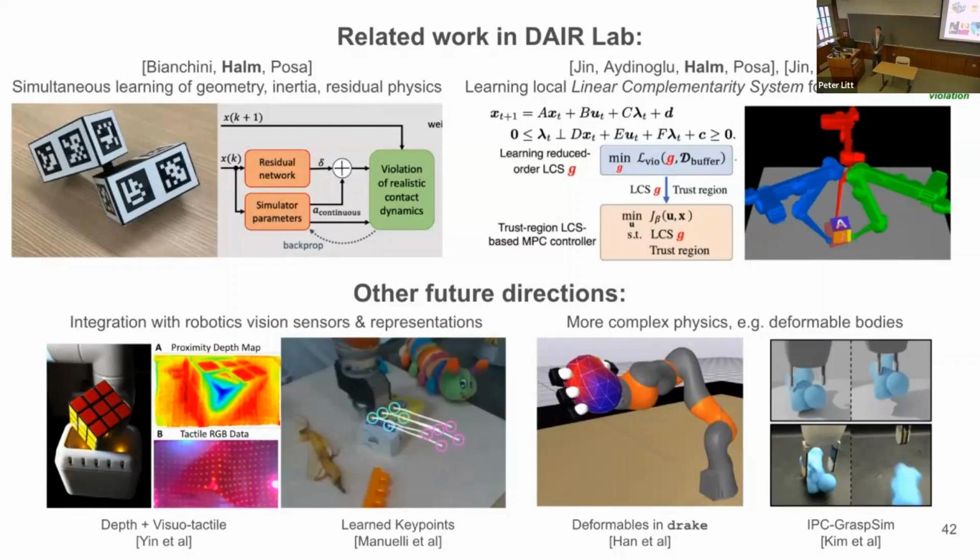Excellent work. I'm curious if you looked into leveraging analytical contact models, like first contact models. Right, lack of plasticity. So there are some simplifications and discretizations of those types of models that do exist in rigid body simulation as approximations. One I'm thinking of is called hydroelastic contact. It's in a popular simulator called Drake, where it's actually looking at the volumetric overlap of supposedly rigid bodies and then backing out an approximate stress-strain relationship that is going to happen due to those overlap patches.